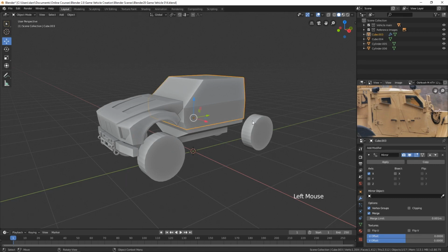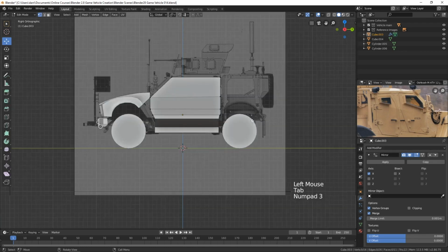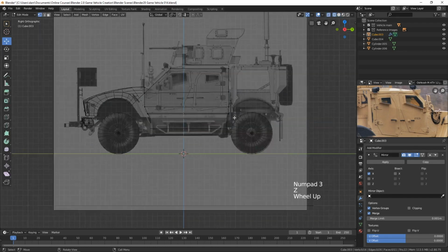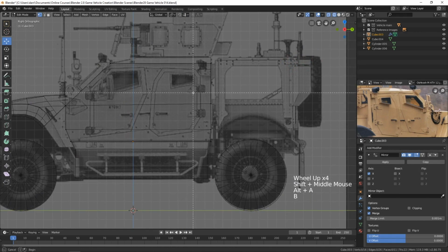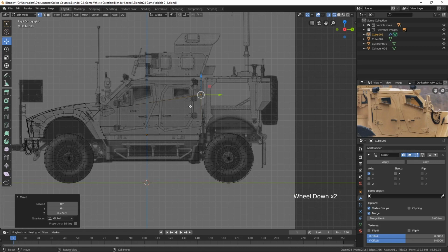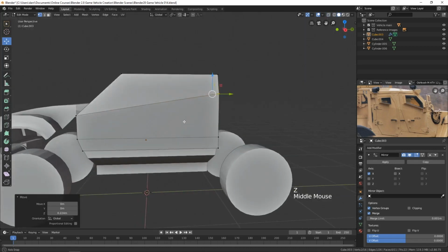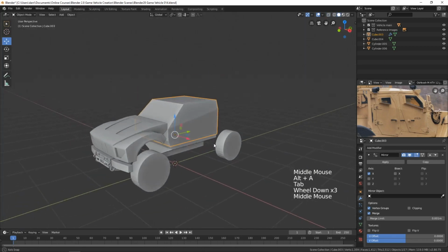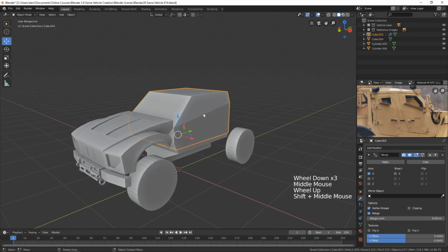And it looks like it's in line with the bottom of the back window. So what we could do, I think, let me go to the side view here and let's go to wireframe. What we could do is grab this point right here and just drag it up so this edge is in line with the bottom of the window right there. So now we take a look at that. Yeah, so now you can see that's that angle. I think that's the way we want it.